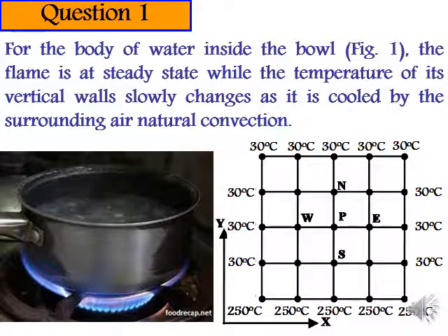The surrounding air is getting warmer when it touches hot bodies, so that this warmness is going to change its density so that it can set some slow motion, upward motion to raise the lighter bodies of air and replace with heavier bodies of air. So this is the natural convection. It's a slow motion, it's a slow mechanism for heat transfer.